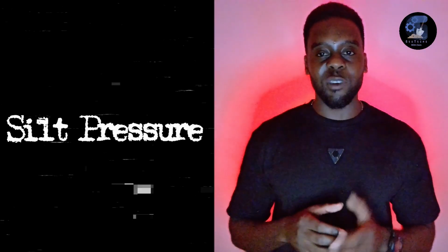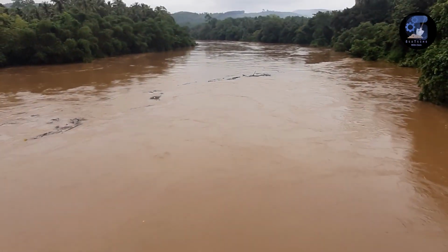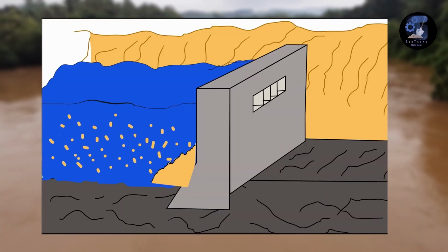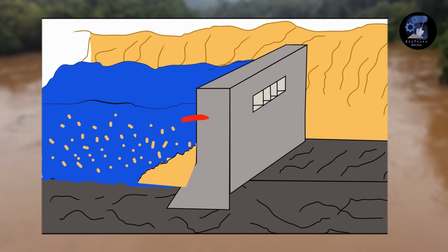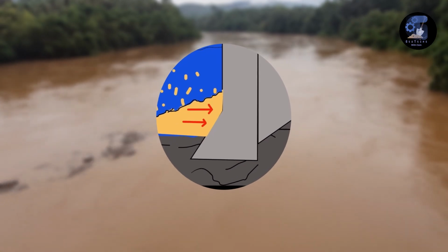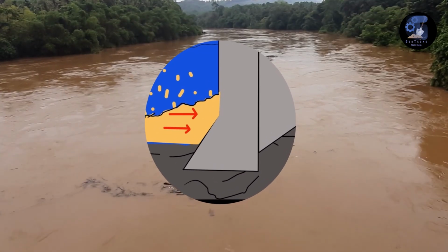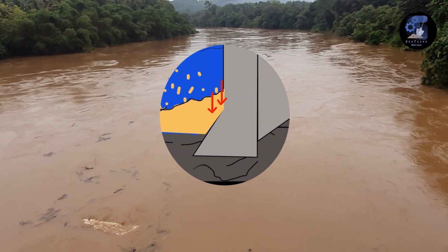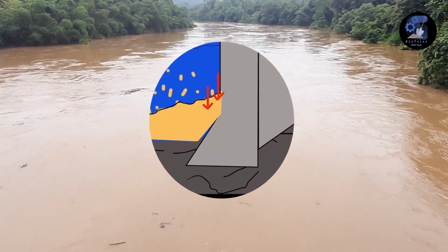When water is flowing in the river upstream, it picks up some loose pebbles, soil, and vegetation. These suspended particulates are deposited at the base of the dam, forming a thick silt layer. This silt exerts a horizontal force on the dam. If the upstream face is inclined, the silt, which is supported on the slope, will also act as a vertical force.